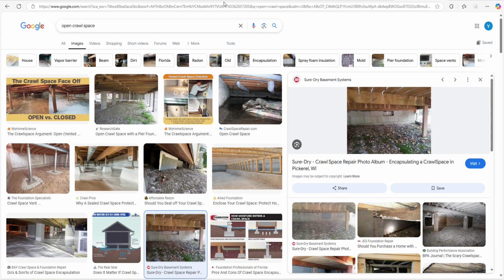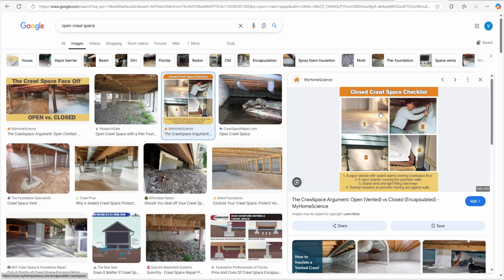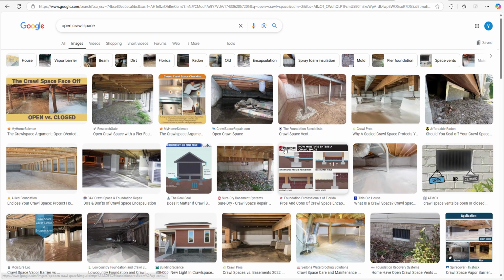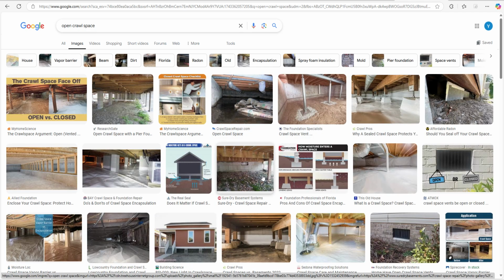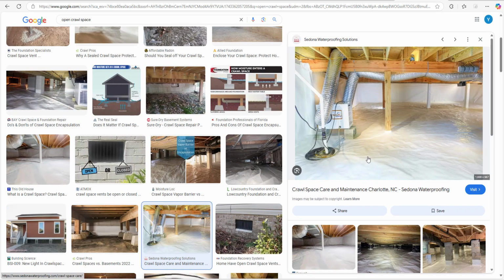Excuse me, my apologies, I was interrupted. I was talking about the crawl space. It's very typical for homes to have a crawl space under the home, exactly like you see here. There's a man under the home. Most often they look something like this: unconditioned, meaning there's no insulation and it's not sealed off from the environment. A newer solution is where they waterproof them, and you might even see insulation, and they're a little more closed off from the environment.